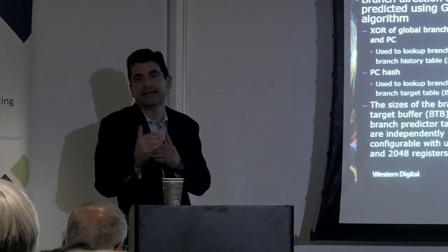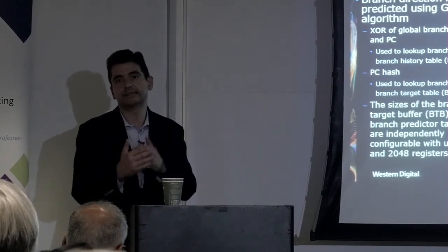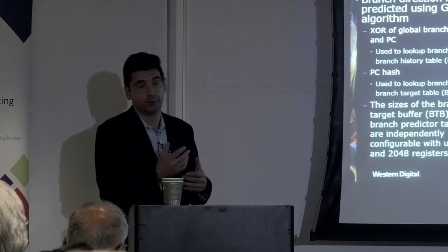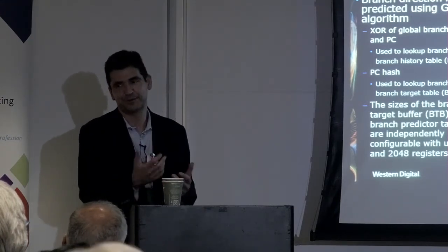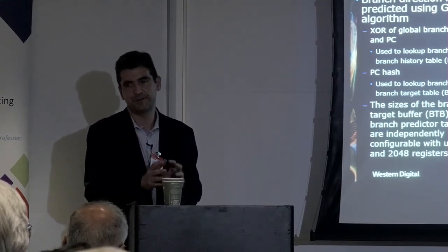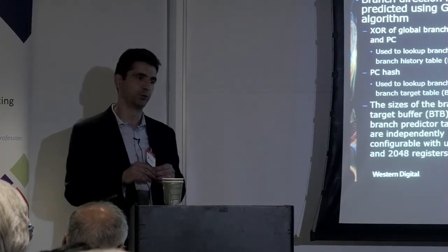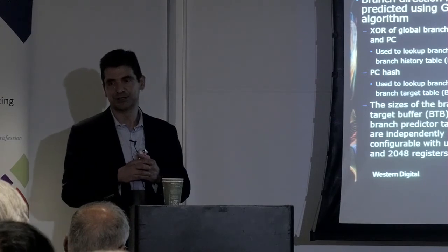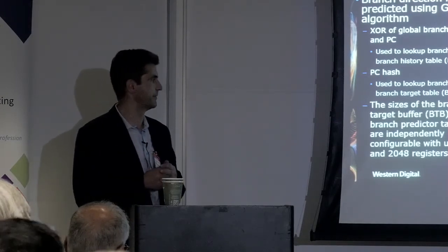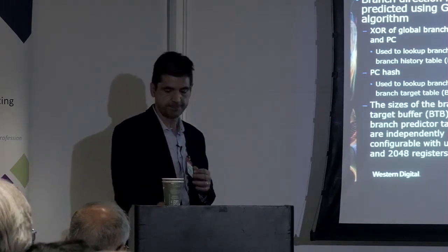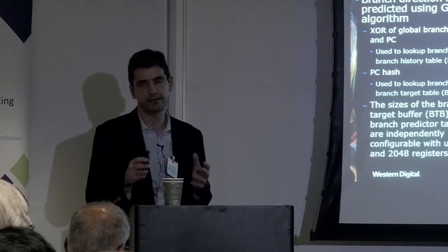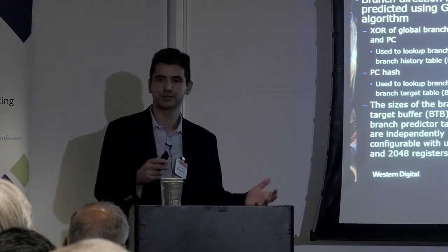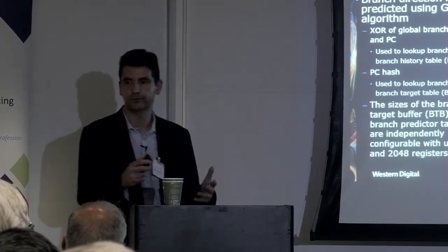When you go to the next level, it becomes too much hardware, too big. You can always take advantage of better branch prediction, but you want to keep the size of the registers and SRAM to some reasonable value. This has been done really well, and we discovered that our branch prediction beats some commercial products that claim the same algorithm and configuration with the same sizes.